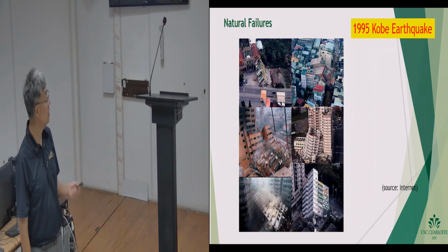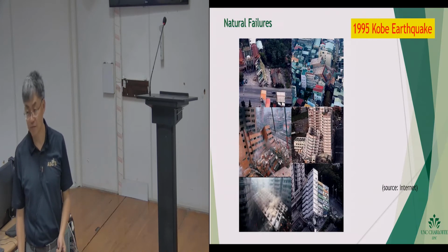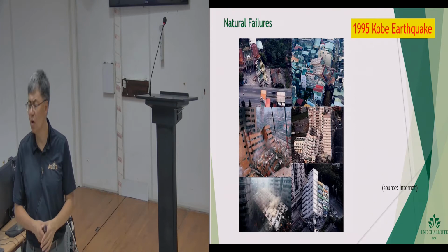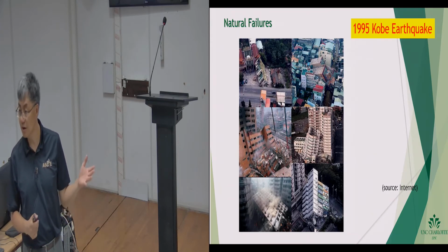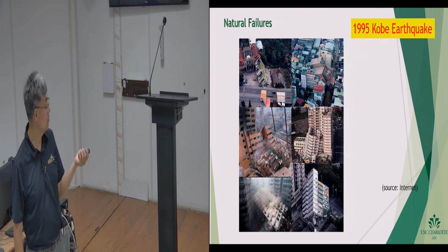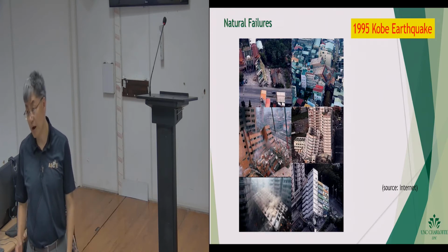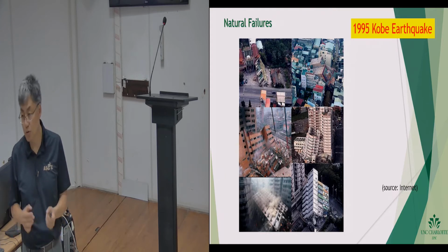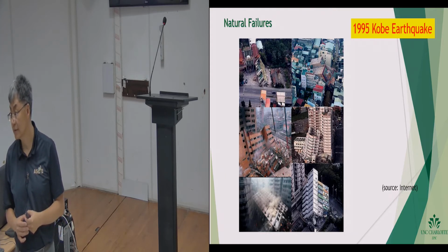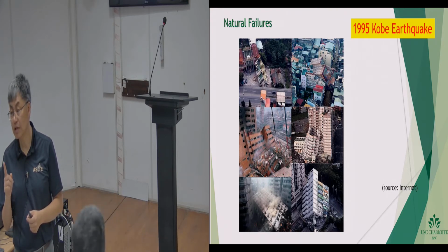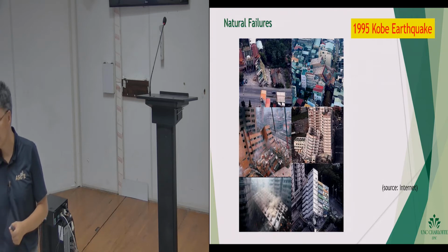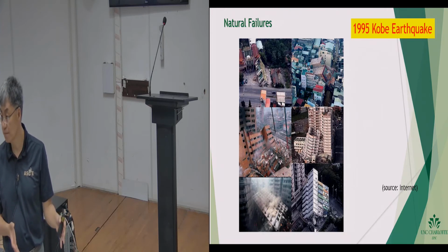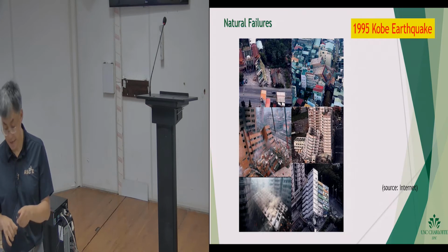There are some really amazing failure investigations, like the Kobe earthquake. In this case, the entire building collapsed. You almost don't have to argue why. We know it's the earthquake, right? But still, the insurance company will work very hard to argue the case. Many times the argument in this case is whether your building foundation liquefied. The reason is that in many countries, earthquake design and liquefaction of the soil are two separate issues.